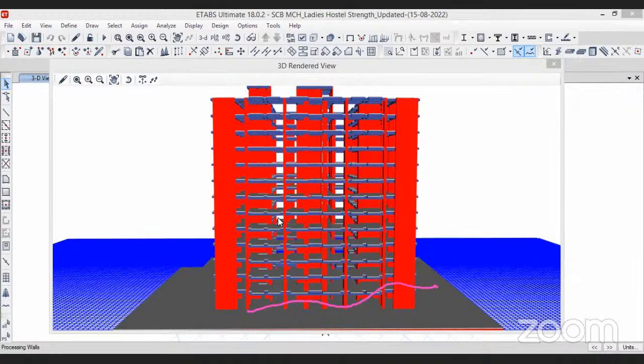Sir, is the structural design of beams and slabs of each floor the same for the whole structure? I'll tell you, the beams and slabs design will be the same unless you are having a lateral force in your beams. If this is a building of 14 slabs, where you are designing this building under zone 5 or zone 6, a higher seismic zone.